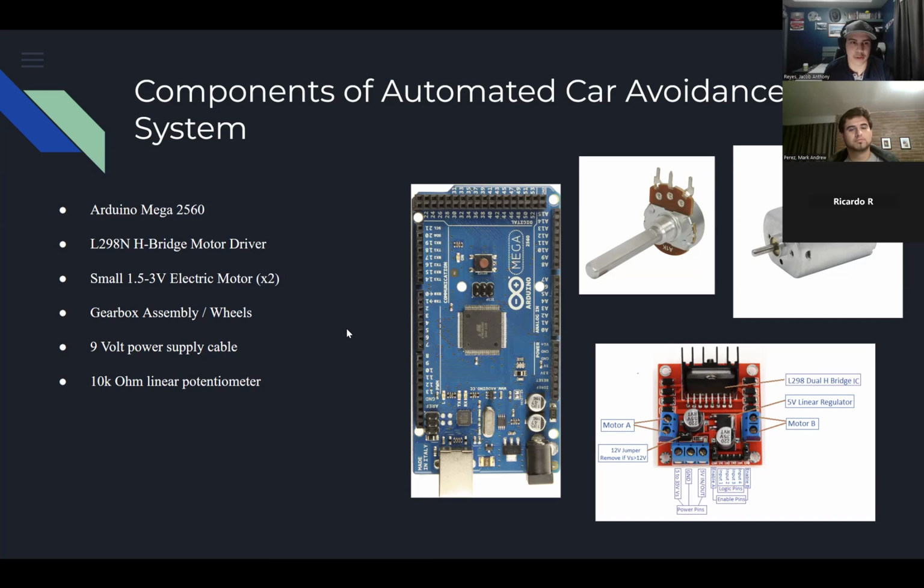For the next component, we use an L298N H-bridge motor driver. This is what drives our motors, since our Arduino does not have enough current or voltage to power the motors individually. We'll be using this along with an external power supply to power our motors.